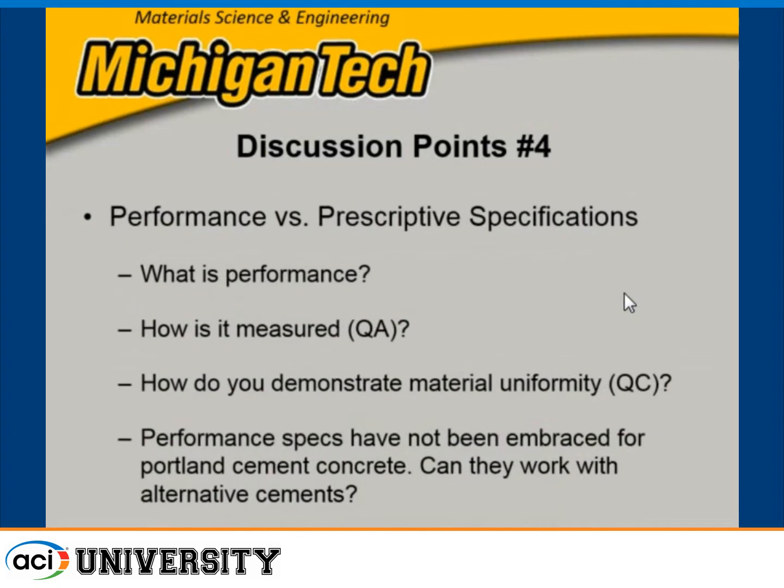Specifications, performance versus prescriptive. We had a lot of conversations about this. In terms of codes and specifications, one of the things we talked around is, can we put out basically a straw man performance specification for these materials? Well, then we start having the same old conversation that we're having with the Portland cement when it comes to performance specs. What's performance? And how are you going to measure it? Particularly if we don't have the right tests. How are we going to measure that performance? Performance specifications have not been widely embraced in the Portland cement world. And there's no reason to suspect they're going to be any more widely embraced in the alternative cement world.